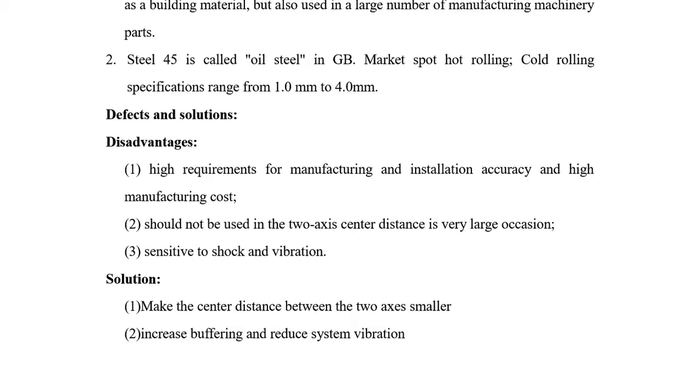About its disadvantages, you can see there are high requirements for manufacturing and installation accuracy and high manufacturing cost, and it shouldn't be used in the two-axis central distance is very large machines, and it is sensitive to shock and vibration.